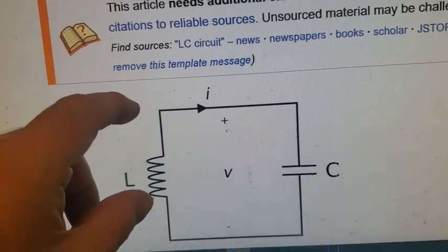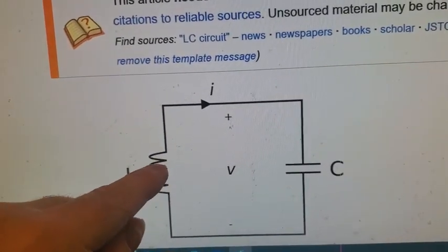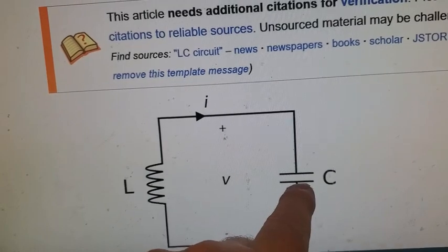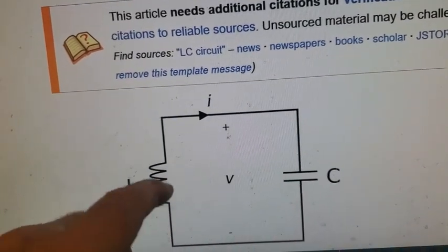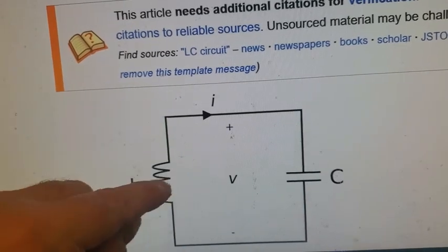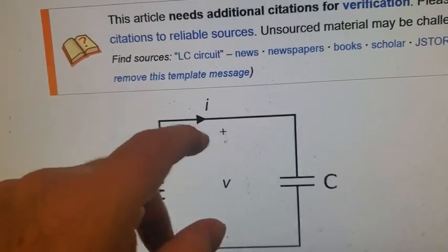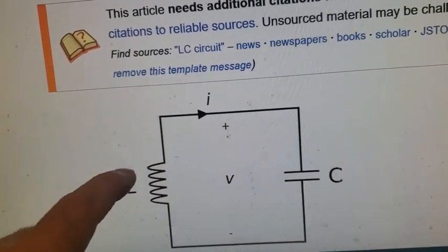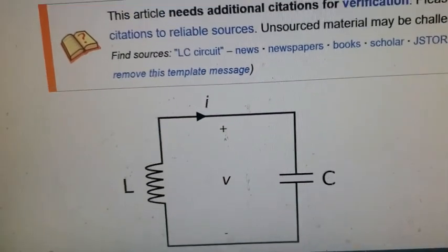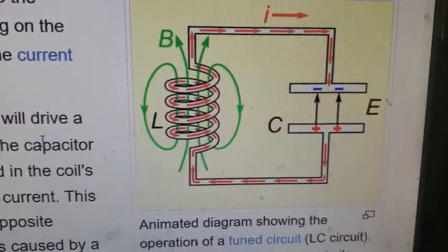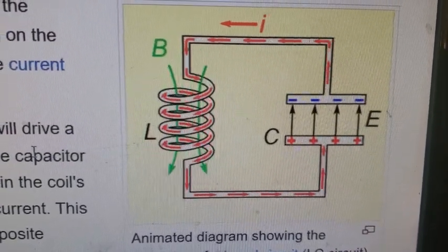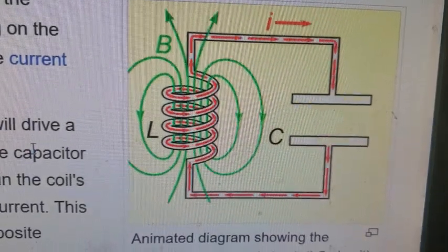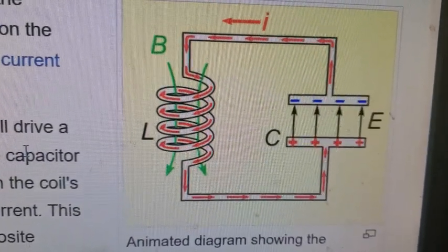But because the field strength is decreasing, it has an opposite polarity. So this will then end up at like -8 volts, as I just said. Then the -8 volts discharges, the capacitor goes with the field strength strengthening, and then goes back, and this goes to say 6 volts, and then -4 volts, and then 2 volts. And it rings back and forth there. There's a little animated diagram they give us here. You can pay attention to the positive and the negative on the capacitor, and you see that they're changing each time. One plate is positive, then negative, and then positive again.